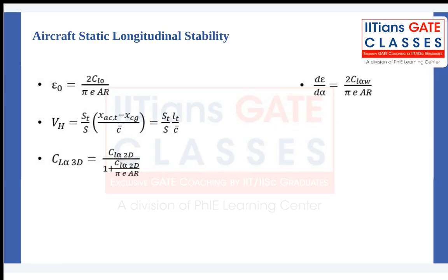So these were the equations that we use when we solve the questions. One thing you need to remember is that all of the quantities in these equations are valid for radians and per radians. Depending on the values given in the question and the unit they've asked for, you can convert into degrees and per degrees. But these equations are inherently derived for radians and per radians respectively. So keep that in mind.